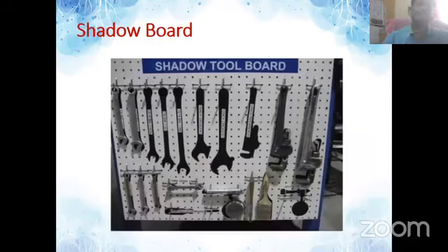Okay. So this shadow board provides us a tool to find out what is missing. Suppose there is a maintenance department, and in the maintenance department there are different wrenches, spanners like that. If some operator finds that a spanner is not on the board, he immediately goes and finds the missing tool. This is the kind of lean manufacturing technique which helps us save time. It saves the time to find any tools or equipment needed for maintenance purposes.